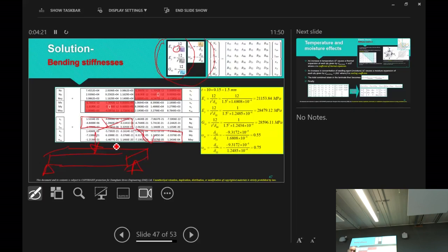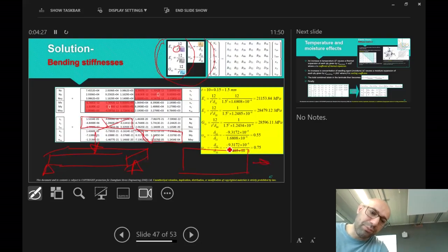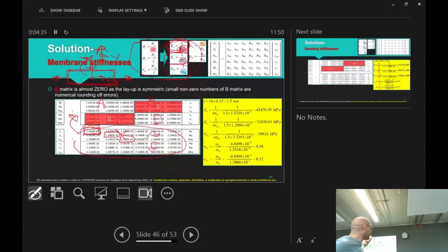But if you've got a structure which, as I explained, is a simple plate, and you pull it apart, the loading is in the plane of your structure. It's not bending, so you need to make use of EX and EY from the previous slide. That's something to bear in mind for further calculations, or if such a scenario crops up.